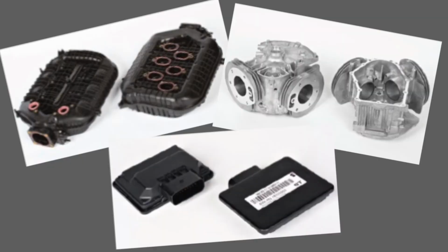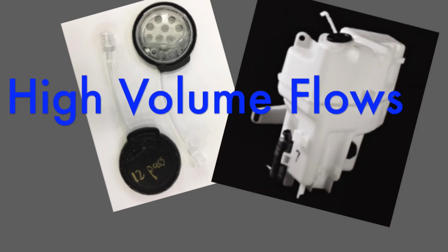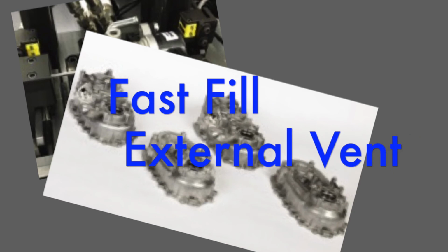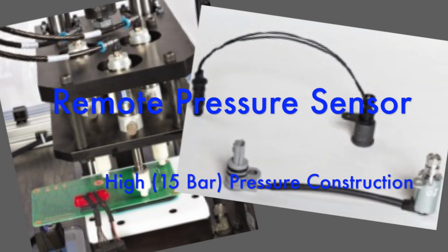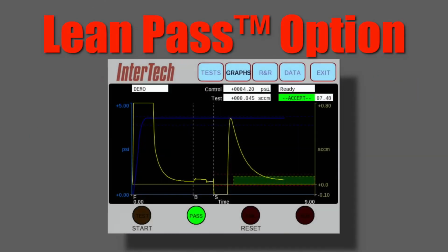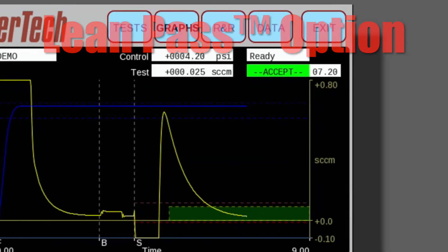The InterTech M1075 is available for both vacuum and pressure applications as well as high-volume flow testing. The M1075's many options include fast fill, external vent, programmable regulator, and an additional 20 I/O for machine control. InterTech's proprietary lean pass option can further reduce cycle time by passing an obviously good part as soon as its leak rate, measured in real time during stabilization, falls into the user's preset acceptable range.